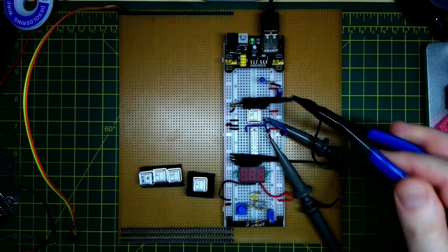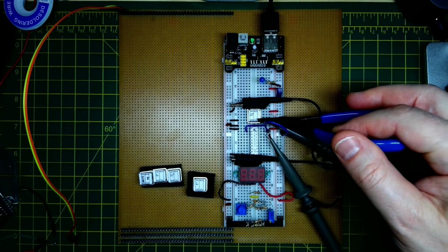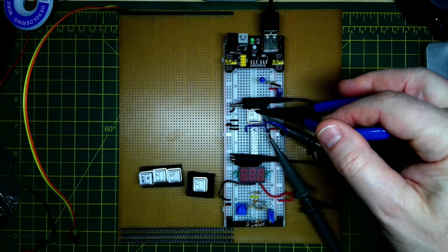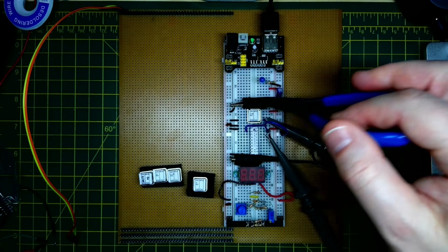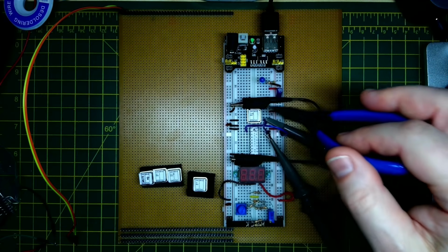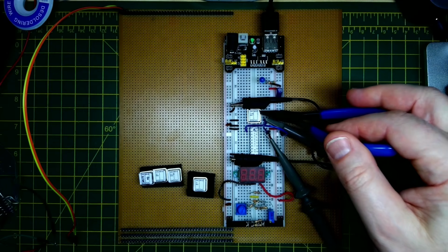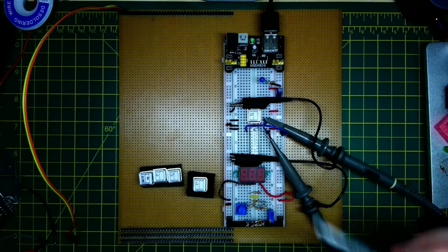So what I've actually done here, I've taken out the LEDs other than the power LED. What I've got is a crystal oscillator, or it's actually not a crystal oscillator, it's an oscillator package which has an output here, 5 volts, ground there, and the other pin I don't think is connected. And I've found these to be much more reliable for getting oscillators in breadboard circuits. Trying to get the crystals and the inverters with the necessary capacitors and resistors oscillating has sometimes been challenging, but these things seem to work every time.